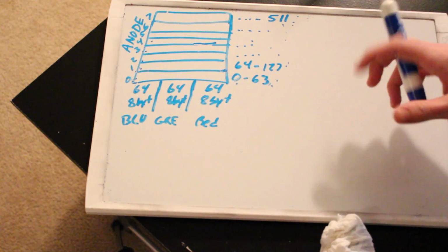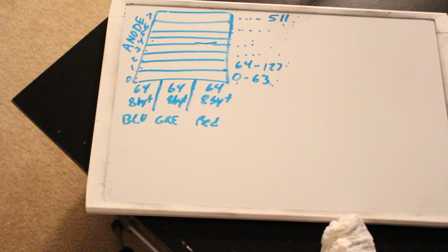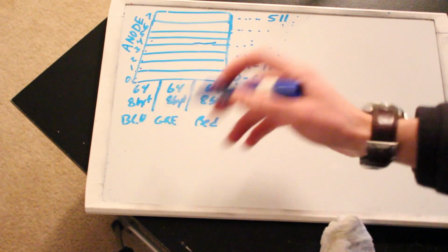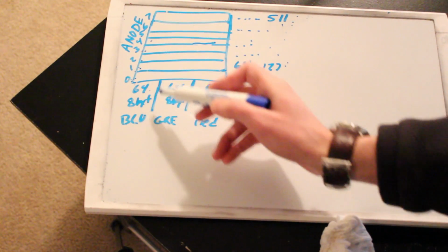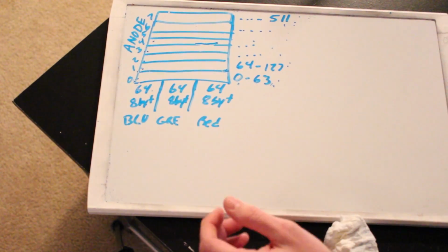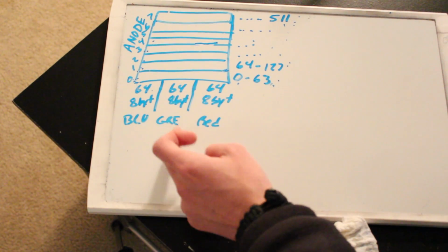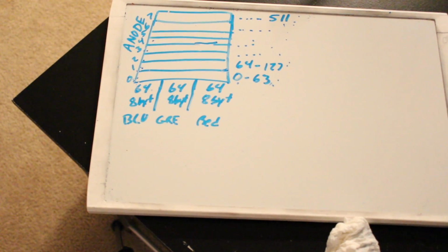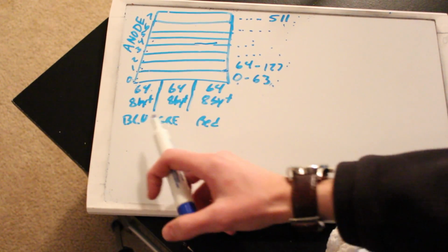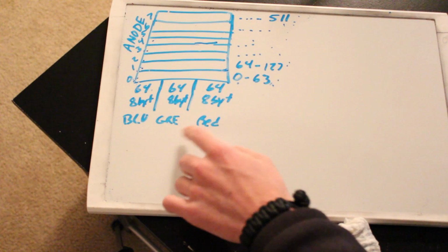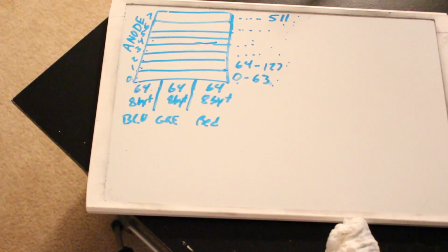So if you look at a cube, if you're looking down on it, you have an 8x8. So you have 64 pins per color coming down for the cathodes. So 64 pins coming down, and that's 192 total. 64 pins is 8 bytes of data. So if you have 8 shift registers per each color, which we do have, each one of those pins can go into an output of a shift register, essentially. And you've seen the theory video and how that works. So we have a blue, green, red array of shift registers, essentially. So we have 8 blue, 8 green, 8 red, and then we have 1 shift register for the anode control.